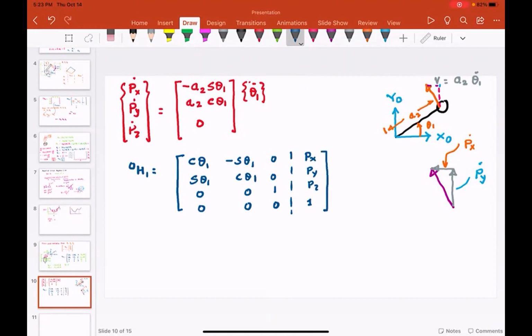Now, we didn't do this process here, but this rotation matrix, and this is super duper important, is basically the product of two matrices. The product is 0R1 multiplied by the projection matrix. Do you agree with me? In this particular case, since the 0th coordinate frame and the first coordinate frame are aligned, the projection matrix was identity.